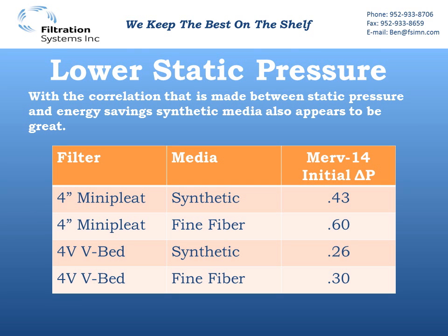Well, static pressures. This is another thing that made synthetic medias look like a home run. Made them look really, really good because we had a correlation between the initial static pressure and the energy that the filter is going to use. If we have a lower static pressure, that means it uses less energy to move air through it, which is true, but how quickly does that initial static go up? We'll talk about that in a moment.